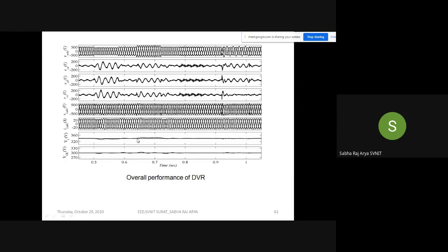If we have a 340 volt PCC voltage amplitude, and after tuning that voltage has increased and is not returning towards the original value, then that is a problem of the PI only, not a problem of the control. We need to tune the PI so that it returns towards the reference level. Here it is not returning to the reference level. It started returning, but again after some time it has increased. This is the problem of the PI only.